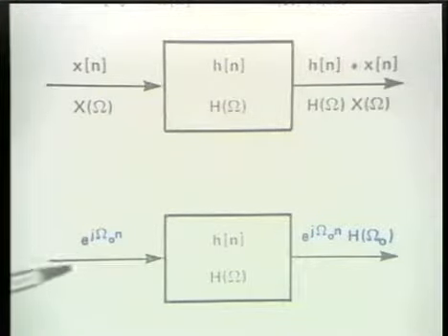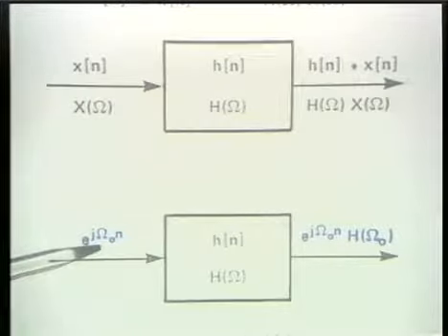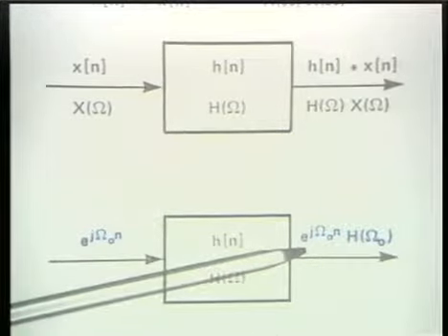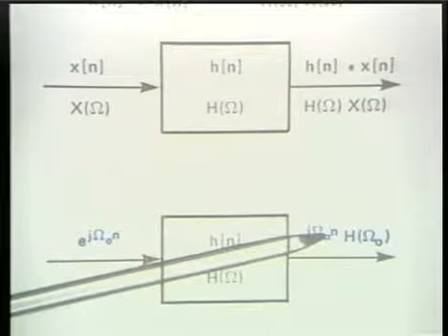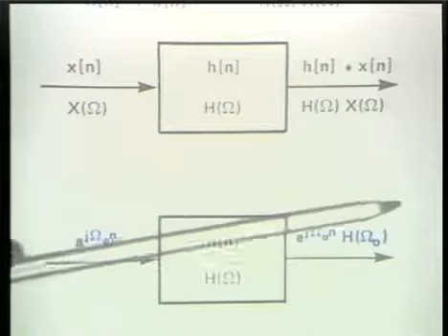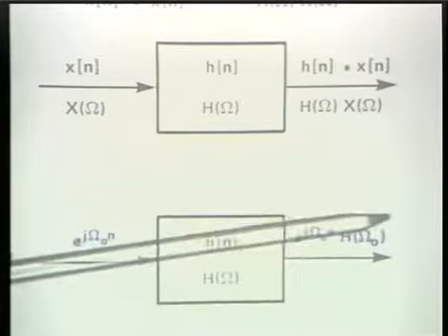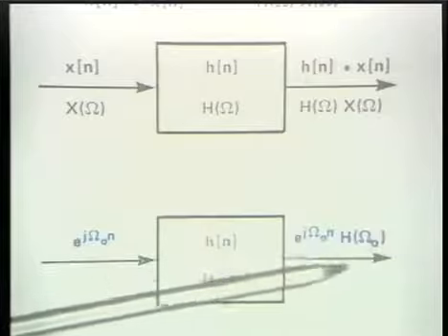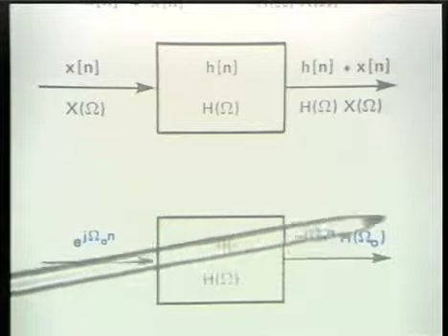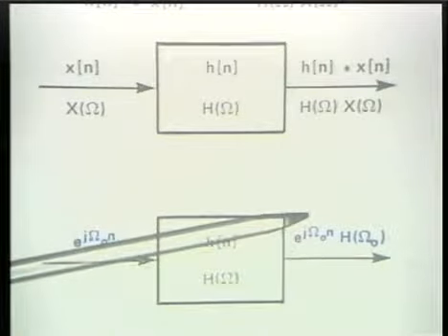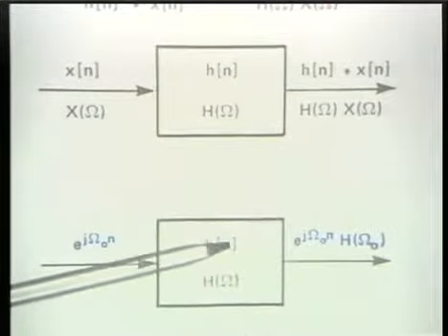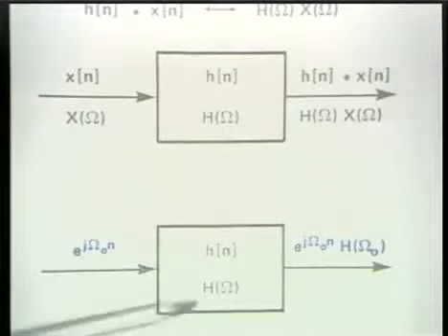Specifically, complex exponentials are eigenfunctions of linear time invariant systems. One of these into the system gives us as an output a complex exponential with the same complex frequency multiplied by what we referred to as the eigenvalue. And as you saw in the video course manual, this eigenvalue, this constant multiplier on the exponential, is in fact the Fourier transform of the impulse response evaluated at that frequency.